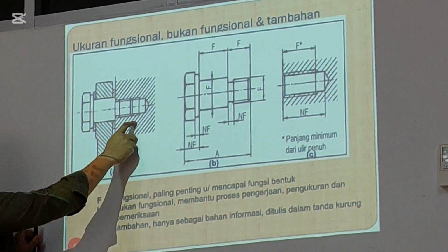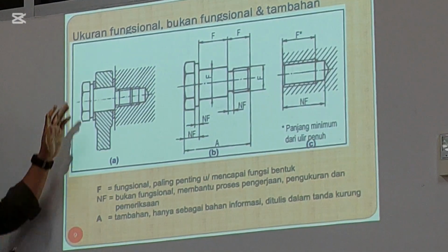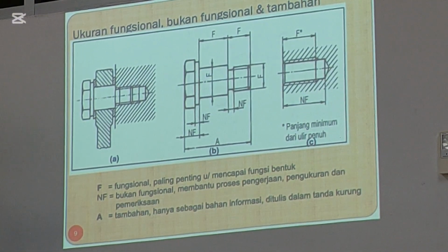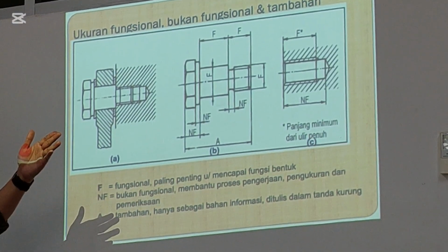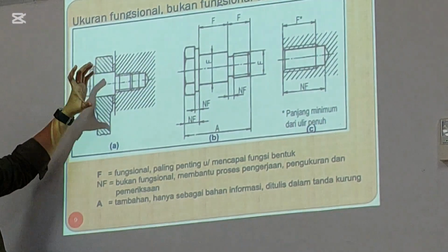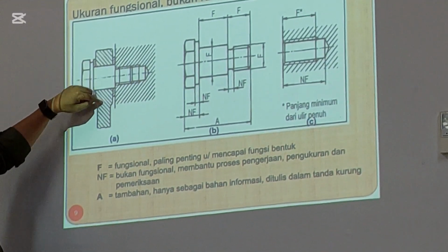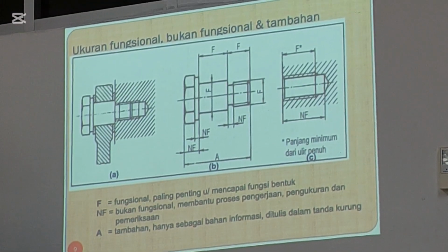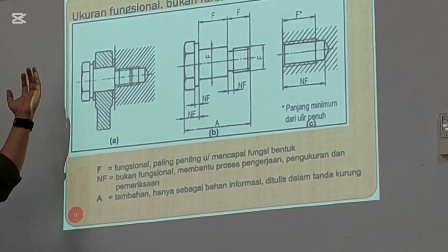So if you find a drawing with any hatched area, it means that this drawing was divided into 2 pieces, cut by some plane. So if you see this hatch, it means that this drawing was cut into 2 pieces, and you remove the front side. So only the rest of the back side remains.